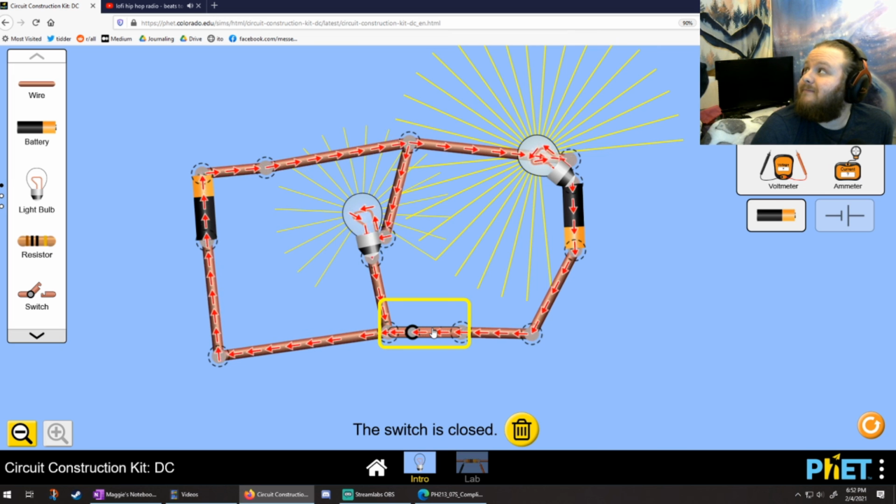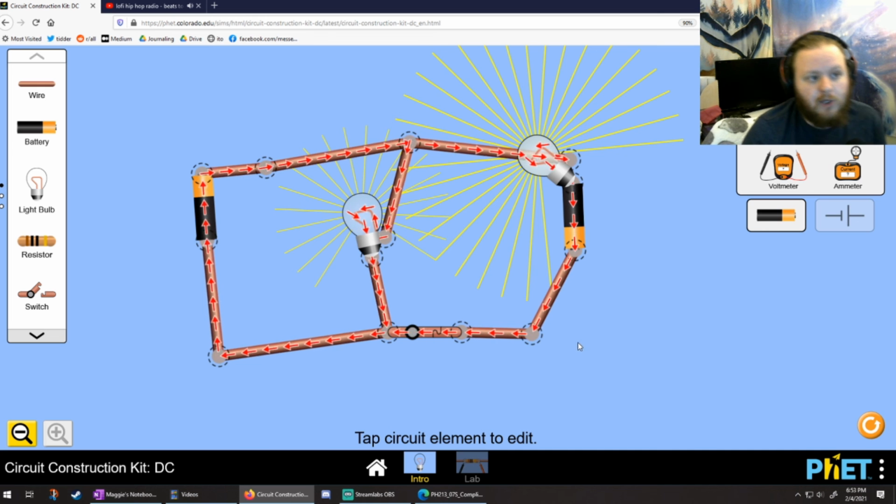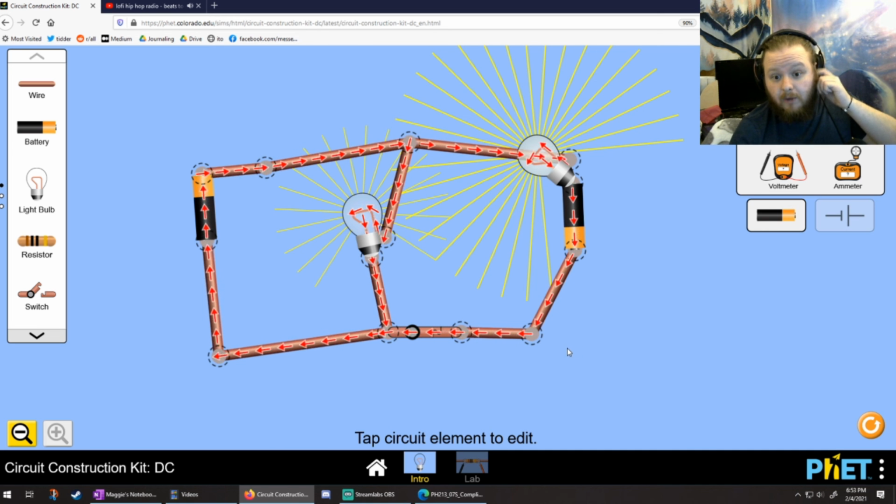Is it the current moving twice as fast, or? Well, I mean, those are the same thing. So yeah, there's twice as much current as there was before, because in this outer loop, I mean, the outer loop is weird, right? You have to drop 2V0 and there's 2 batteries. So you've doubled the voltage, which means you've doubled the current on the outside if you're treating these things as ohmic. So spooky.